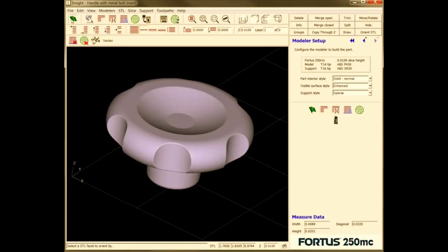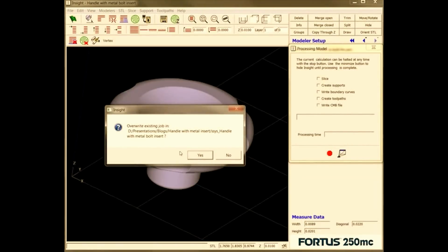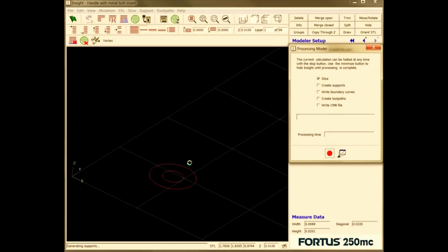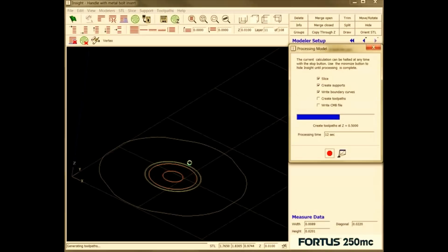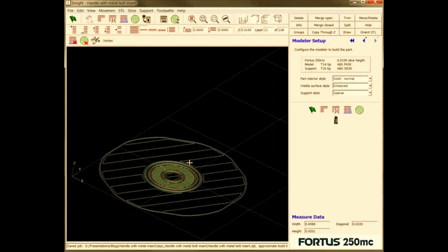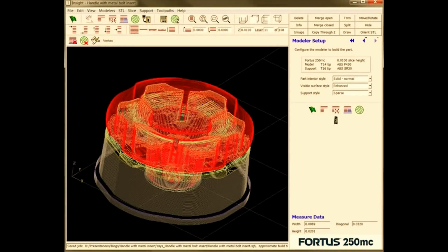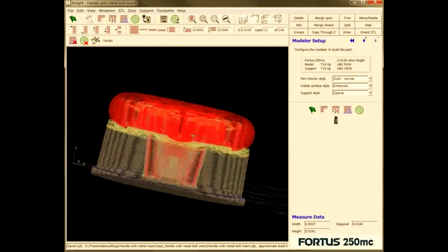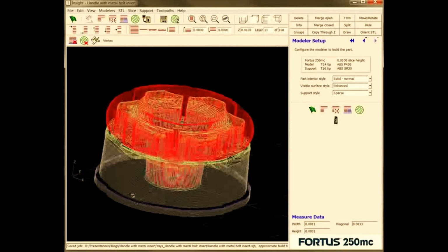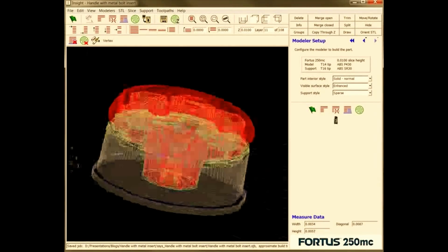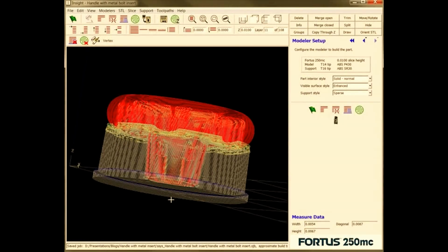So what I like to do is I always like to green flag it and see what the software is going to do, because software engineers are pretty good about how they've developed this and what's going to happen with the toolpaths and everything. And so I'll use what they give me and modify it. So now if we look at all the slices, we can see that it's down on the bed here, the platen, and there's no room for the screw, so we need to raise this up and give it room for that screw that's going to be sticking out.